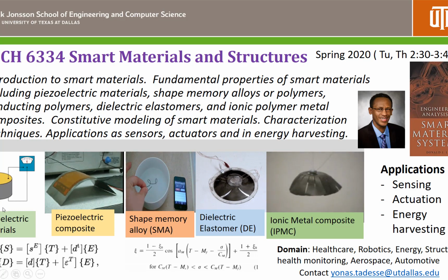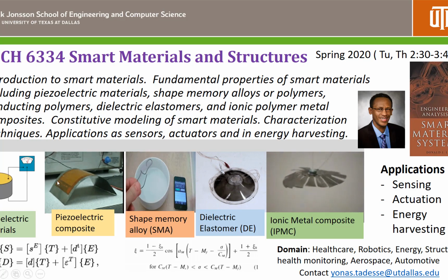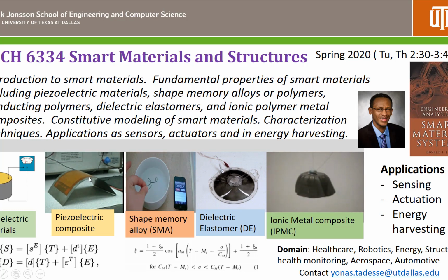We'll study this material more. If you look at this, this is another form, a piezoelectric composite. This composite material, the one that you see in the orange color, is bonded to this steel plate, and the plate is metallic. So when you apply voltage, this is a power supply, when voltage is applied to it, it starts bending. Okay, so now it's operating as an actuator.